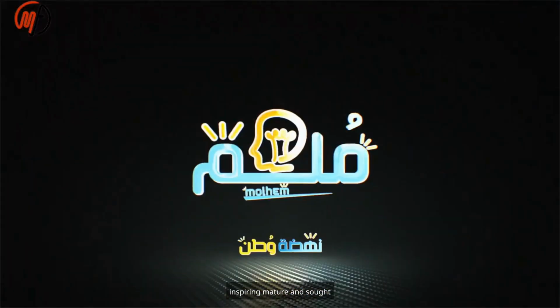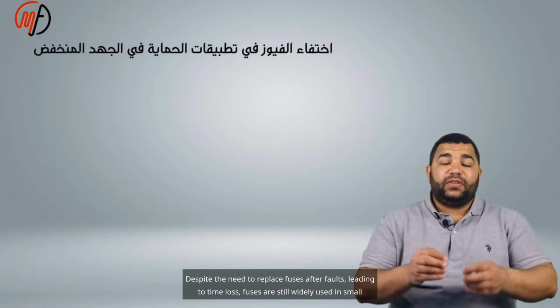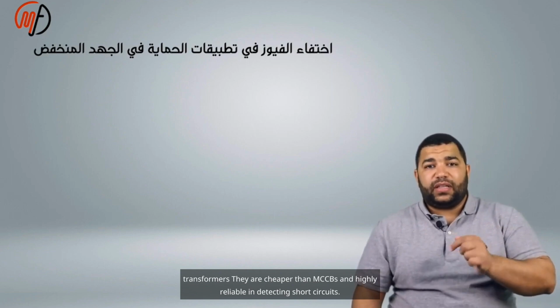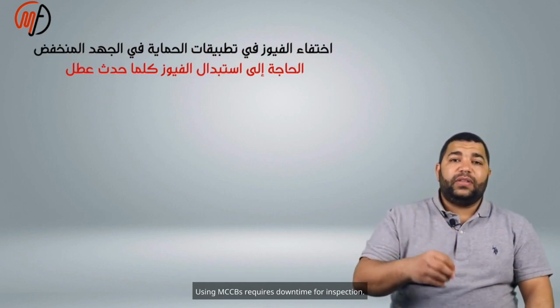Despite the need to replace fuses after faults leading to time loss, fuses are still widely used in small transformers. They are cheaper than MCCBs and highly reliable in detecting short circuits. Using MCCBs requires downtime for inspection.